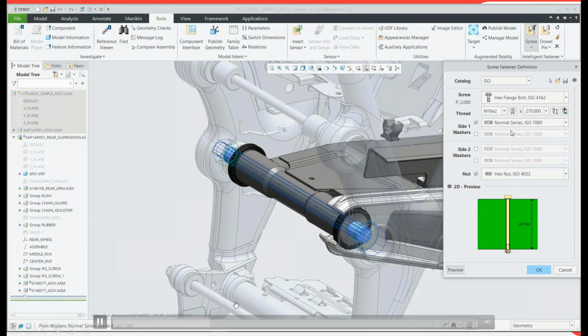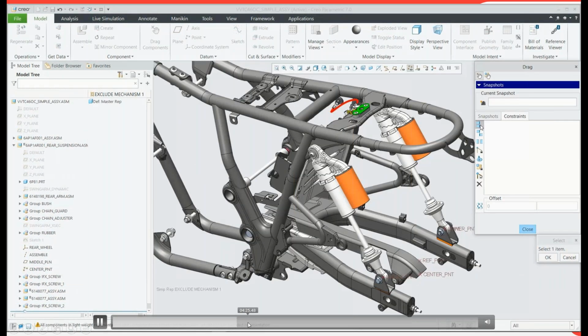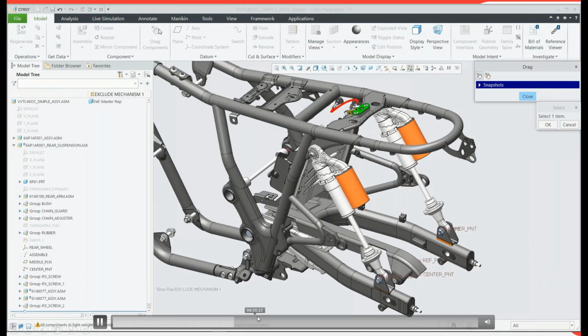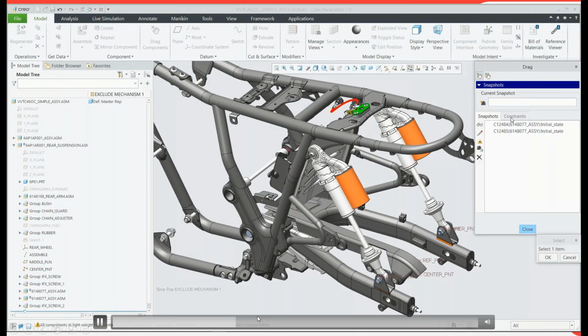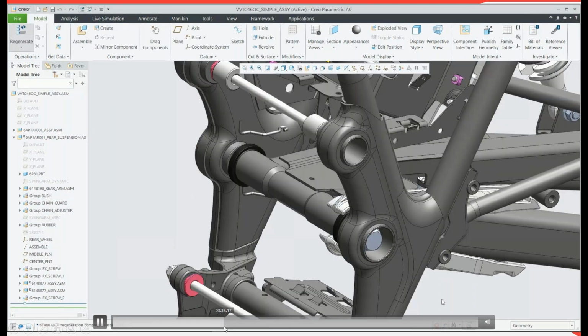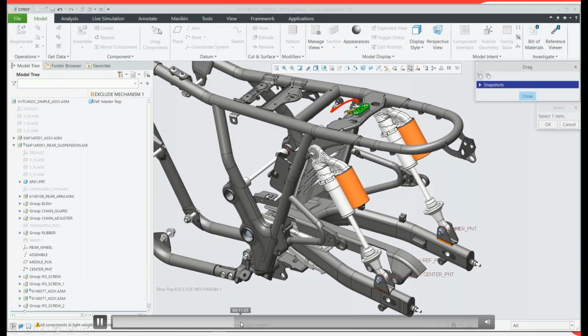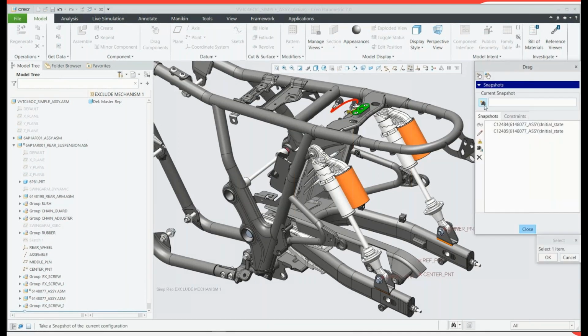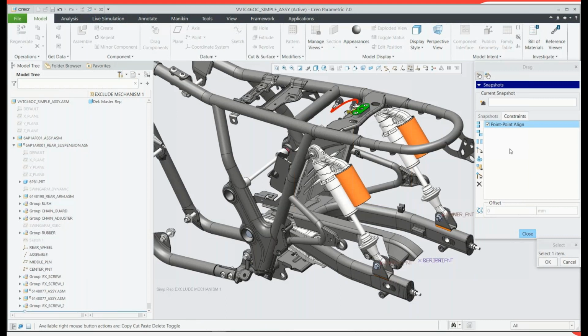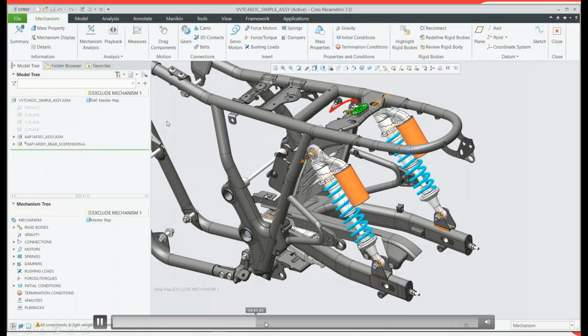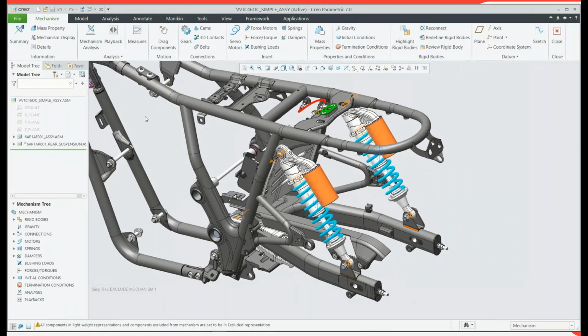But again, if you want to do some kind of kinematics also, you can have a dedicated kinematics environment where you can even design your spring, you can design your dampers, which are going to simulate, right? So it will compress and it will decompress. That kind of phenomenon will also happen when you use this kinematic environment. You just define all the inputs and define that this is the spring, these are the properties of the spring, and these are the connections.